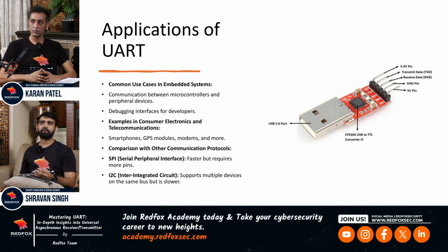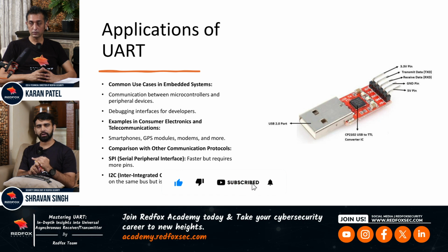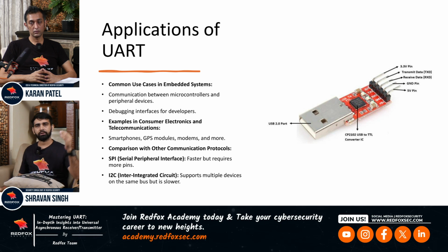The third is GND, the common ground. After connecting RX to TX, TX to RX, and GND to GND, we use Picocom, screen, or the Arduino IDE software so that we can interact with the UART, the boot process and everything, including the root shell access.